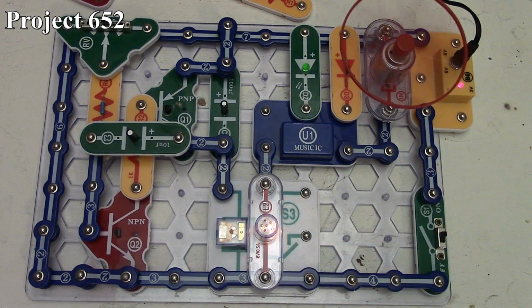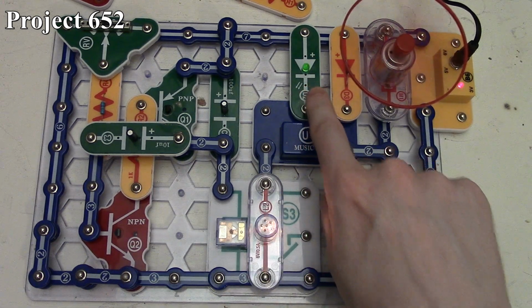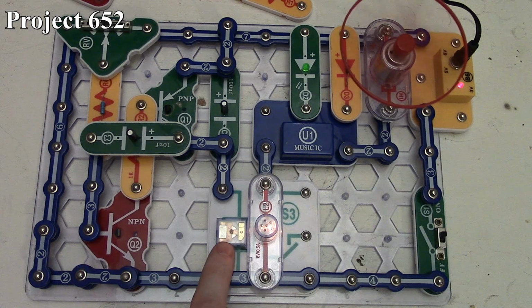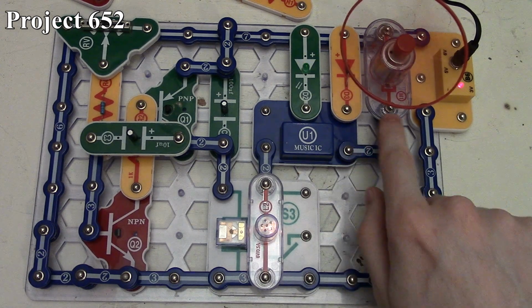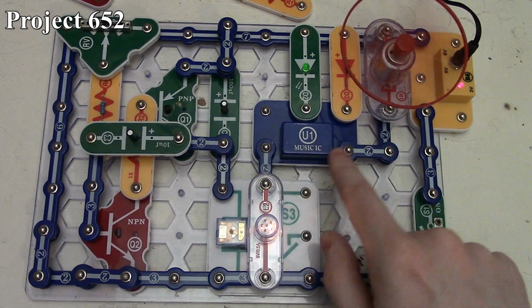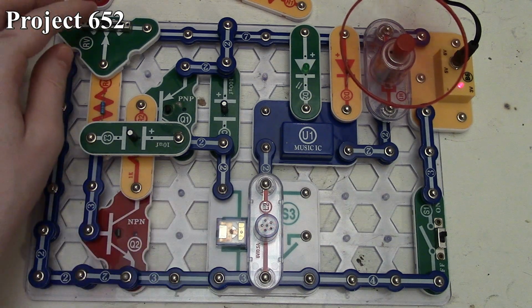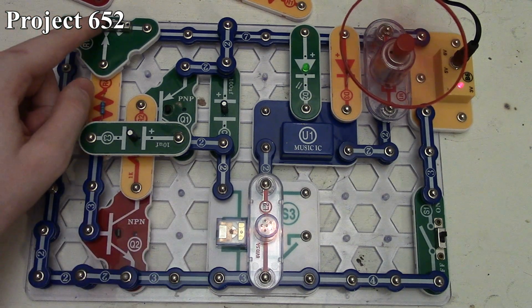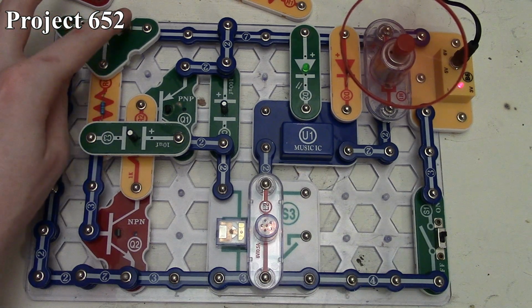Our motor starts up there, and we can see some flashing on our green LED there. We can hear our relay and visually see it clicking away. We can also see flickering on our 6-volt lamp here. And with the motor, we can hear the music IC's output being played back through the motor there because, you know, it's got magnetic winding, so it's behaving like a speaker. And we can, of course, control the level of oscillation by adjusting our variable resistor just like in other projects.